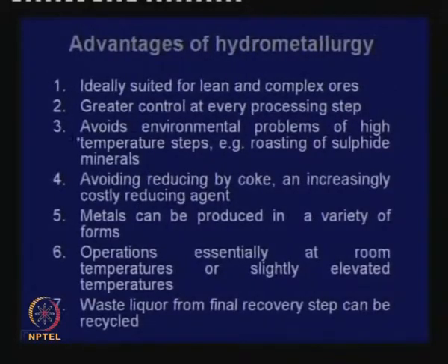We came to hydrometallurgy, saw the advantages, and I mentioned it is ideally suited for lean and complex ores. There is greater control because things are happening at low temperatures, room temperatures very often, or slightly elevated temperatures, but it is easy to control because things are not happening far too rapidly. Environmental problems coming out of gaseous emissions are not there. We do not have to depend on coke as pyrometallurgical operations very often depend on. It is becoming a costly reducing agent. There is no question of CO2 emission.